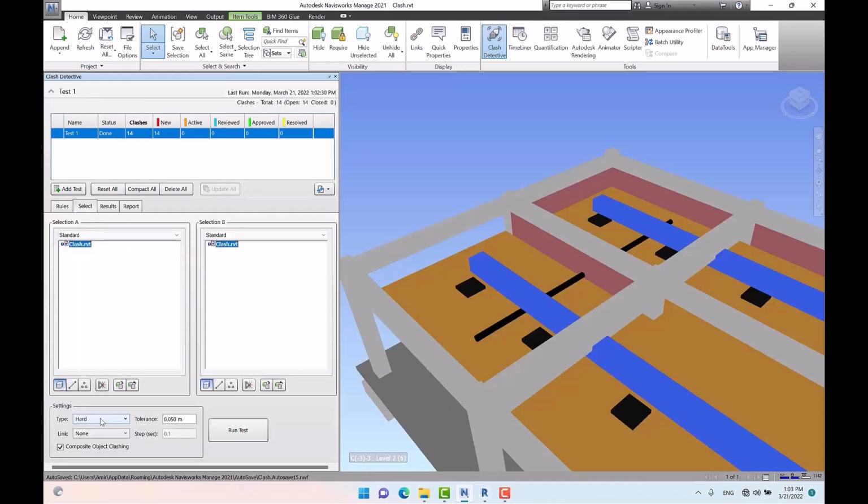Anyway, in the clash detection process, we rarely use the hard conservative type, and we use the type hard to check for intersections between item geometry. We usually set 3 or 5 for the value of tolerance, to not make it that sensitive, since smaller values are resolvable as an intersection. So the standard values are 3 or 5.